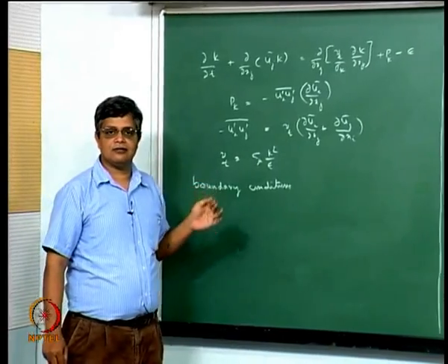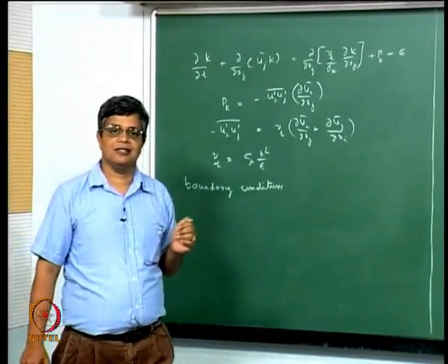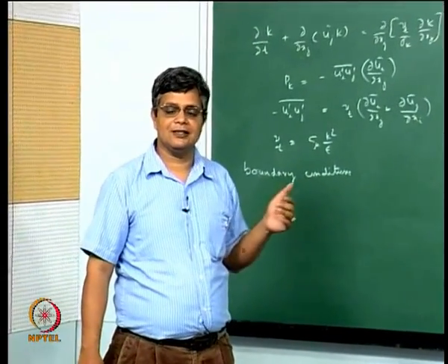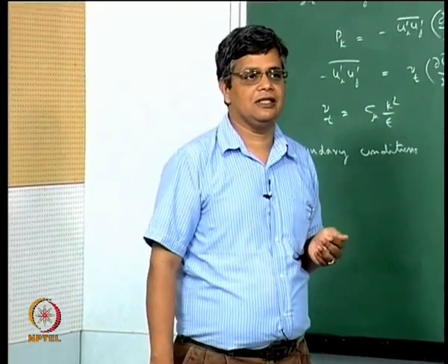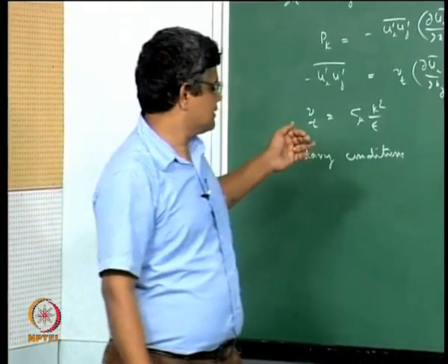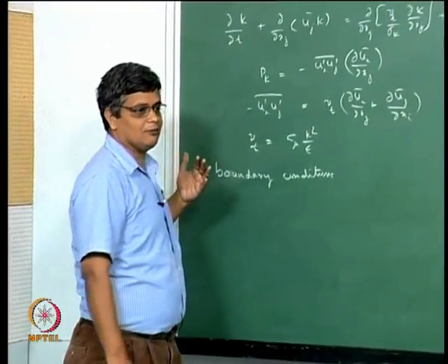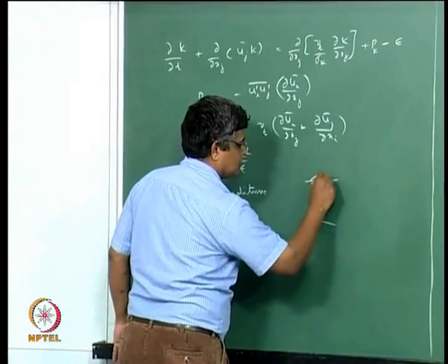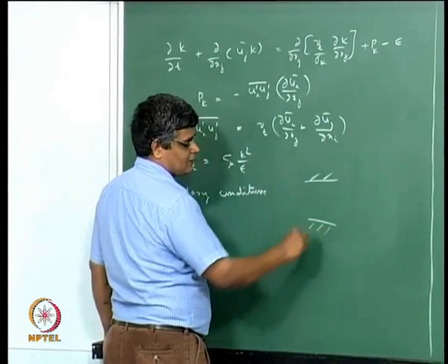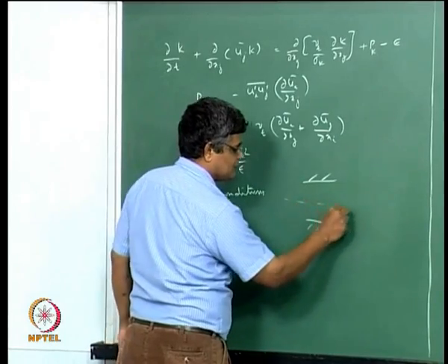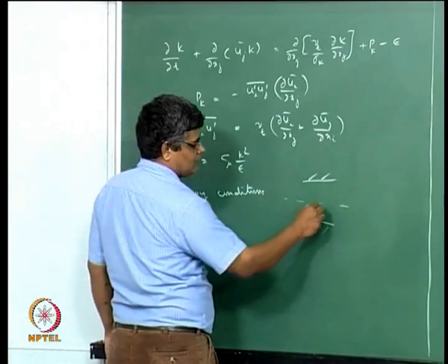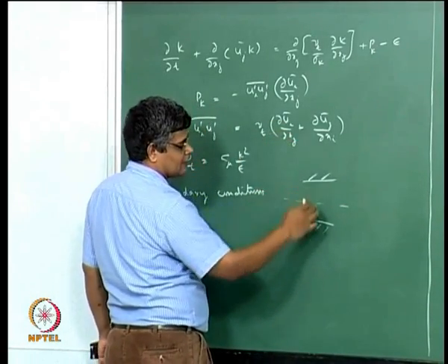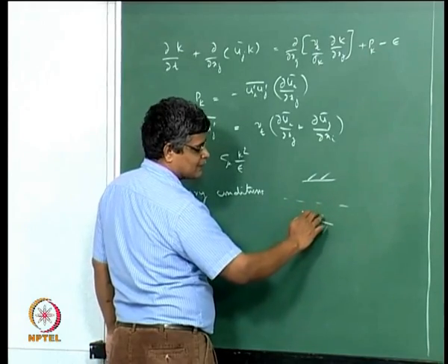So wherever you have standard boundary conditions like a plane of symmetry, and those kind of things, they are still applicable. So when you have a plane of symmetry like flow through a duct which is exactly identical with respect to the center plane, then we can calculate the flow field either in this part or in this part.